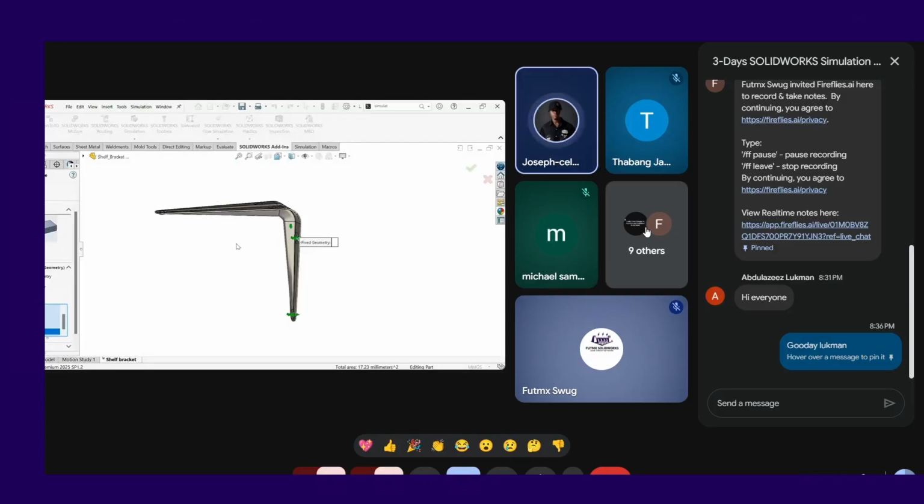Okay, so that's the reason why we are not selecting the faces also. They are not glued to the wall. All right, so fixing the three bolts is more realistic than selecting the part, because you won't get an accurate result. However, the nuance now is that this fixed geometry on the whole assumes that the screw is